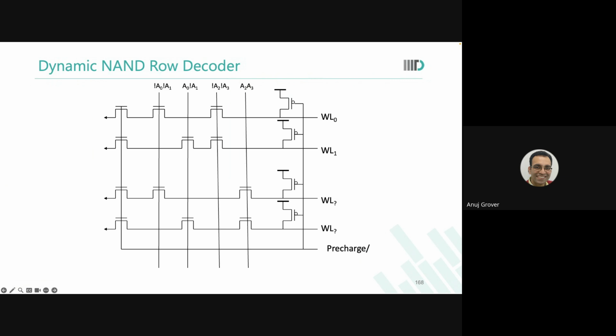One more question that I just had. If we use a negative bitline circuit, I mean that precharge will also become a little bit slower, right? Because I have to trigger it. So the cycle time will kind of degrade when we use a negative bitline.